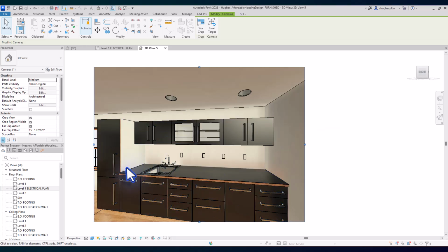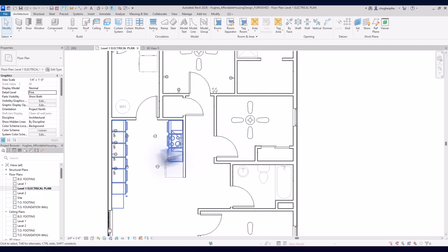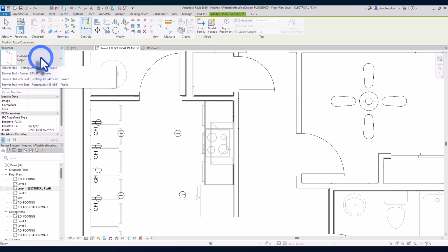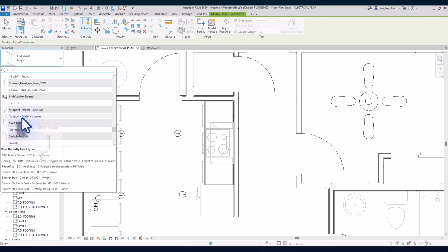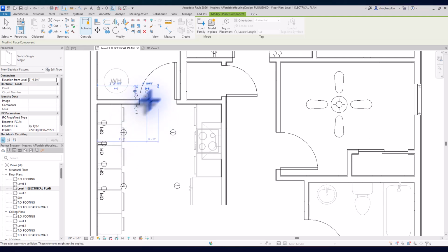So again, I would want to make sure, just by electrical code, placing those GFI outlets and placing those switches. Where would I want light switches as I come into the house? Probably in the kitchen right by the door. I would want to have a spot where I can toggle lights. So maybe I throw on a light switch right here as you come inside, and then maybe also have one on the other side. So as you come into this room, you've got a switch right by the door, so that way you can go in and out.